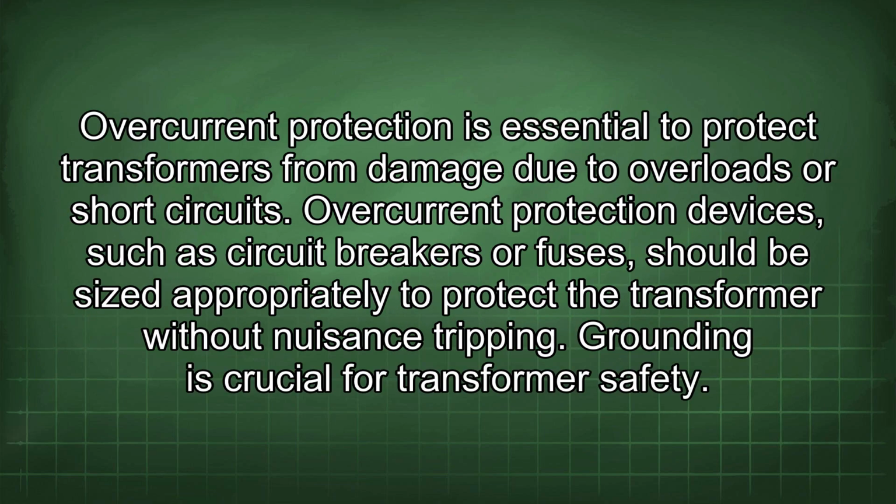Overcurrent protection is essential to protect transformers from damage due to overloads or short circuits. Overcurrent protection devices, such as circuit breakers or fuses, should be sized appropriately to protect the transformer without nuisance tripping.